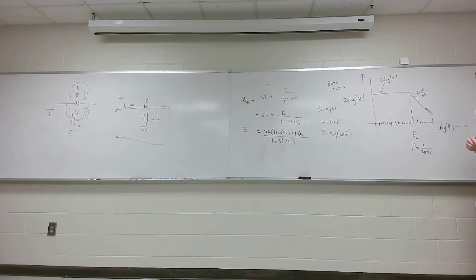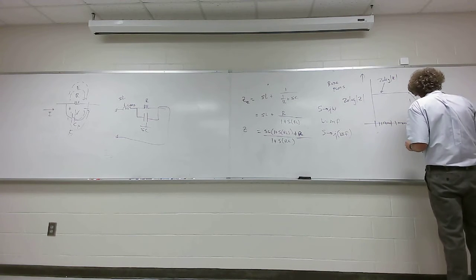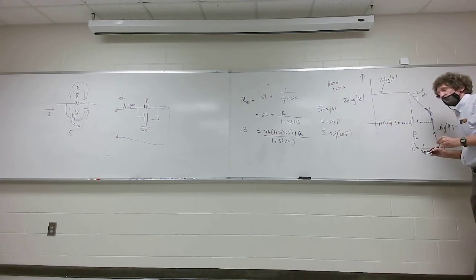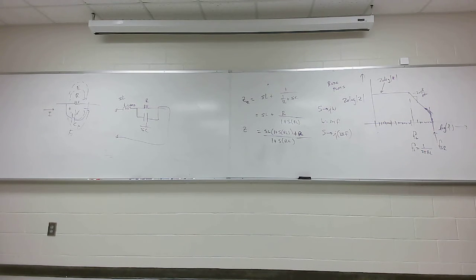Now this is the one that's really critical. It's called the self-resonant frequency. Put a line here and put FSR, it's self-resonant. This is the frequency where the inductor and capacitor resonate. It will be the minimum possible value of the impedance of that circuit right there that represents a single resistor. The F self-resonant is going to be equal to 1 over 2 pi square root of L, and this is the lead L, I'll just put L lead, times C parasitic.